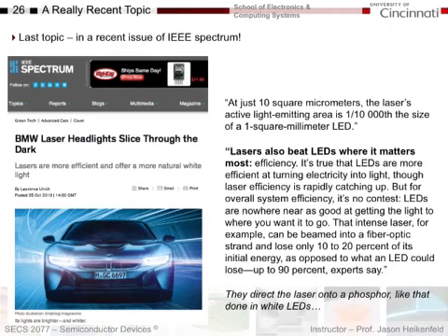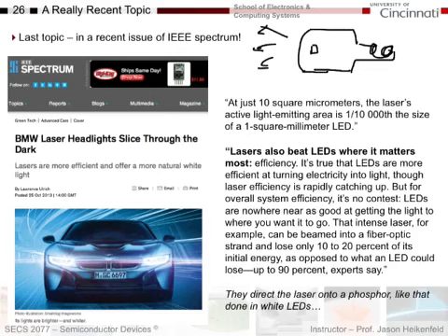In terms of lasers being used in products around us that you might not expect, BMW's most recent car uses lasers for the headlights, and it's not like you think. You're thinking that the lasers shoot out of the headlights. What they actually do is, here's my headlight, and this is my bulb, and I want light emission to come out this way. The laser sits here and hits a phosphor. Here's a reflector. The phosphor converts the blue laser partially to yellow, so I get white light out, which hits this special parabolic reflector, and then I get all my light out.